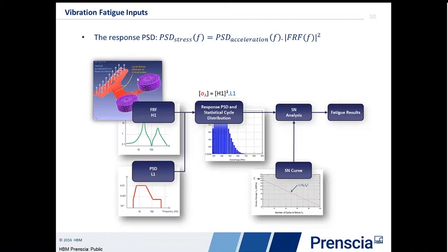What it is, it's a unit excitation, be it acceleration, displacement, or force, across a frequency range. And then the output is a complex set of stresses or displacements or forces that describe the output at each node on my model.